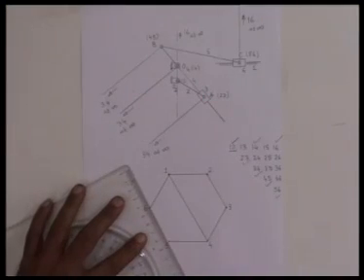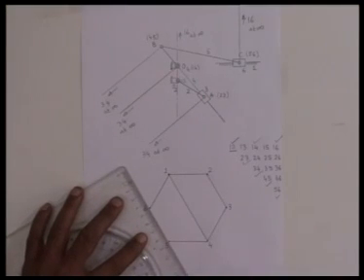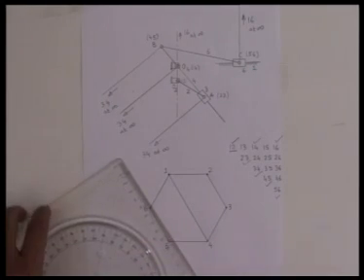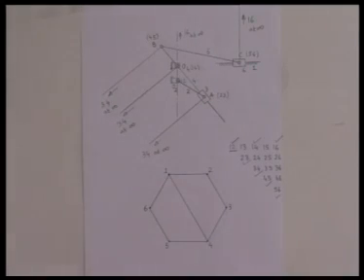So, corresponding to the 7 relative ICs which have already been obtained by mere inspection of the kinematic pairs, I join these 7 lines.